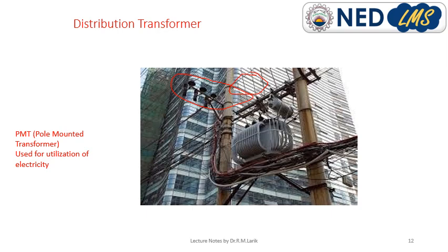So from the distribution transformer we have two options: three-phase supply and single-phase supply. The purpose of the distribution transformer is to convert the transmission voltage to utilization voltage, and that job is done by the distribution transformer. The capacity is normally in kVA, kilovolt amperes. They start from 25 kVA to 500 kVA. Usually in Karachi, we have 250 kVA and 500 kVA distribution transformers.